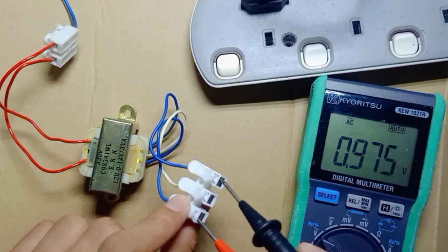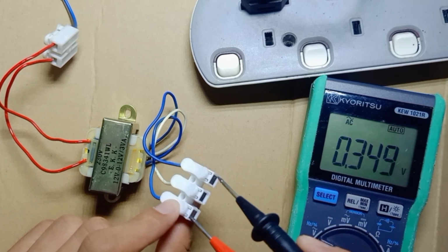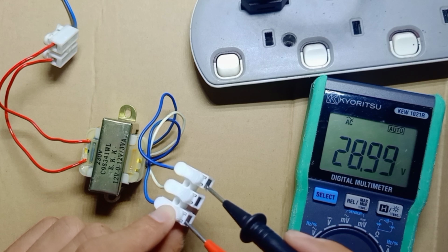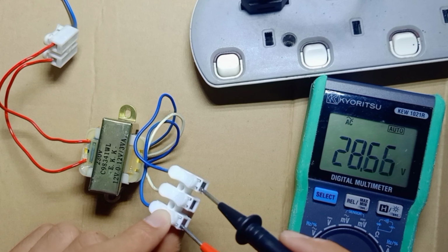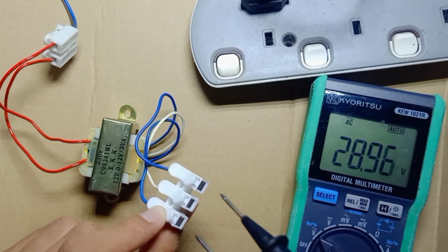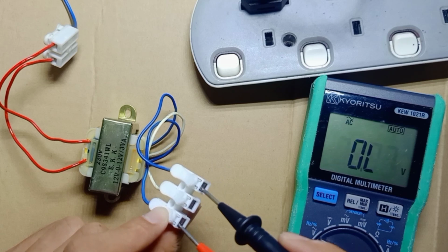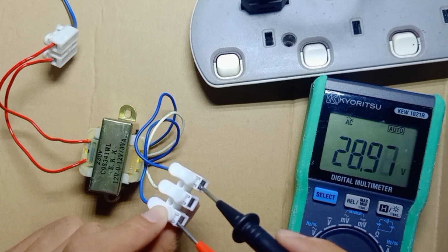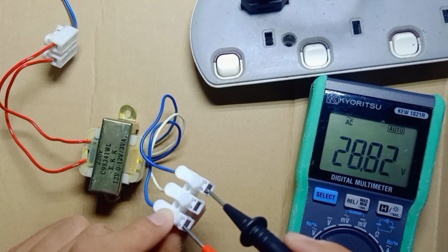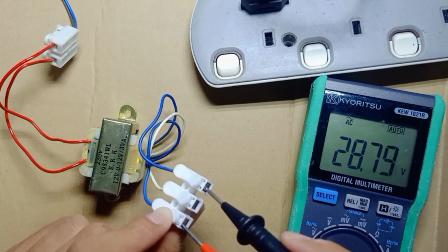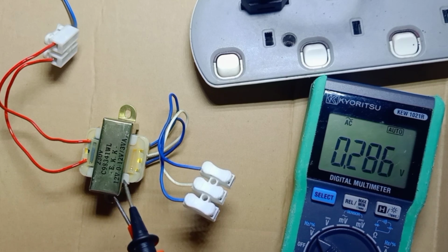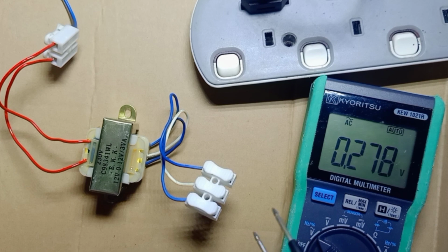So if I use 12 and 12, 12 and 12, how much I get is 28 volt. So this is what we call using the 12 volt as 24 volt output. I'm not using this anymore this time. So 12 becomes 24, 28. Because this is unregulated, it is not constant yet, so we get 28 volt. It means this transformer you can use as 12 volt and you can use as 24 volt.